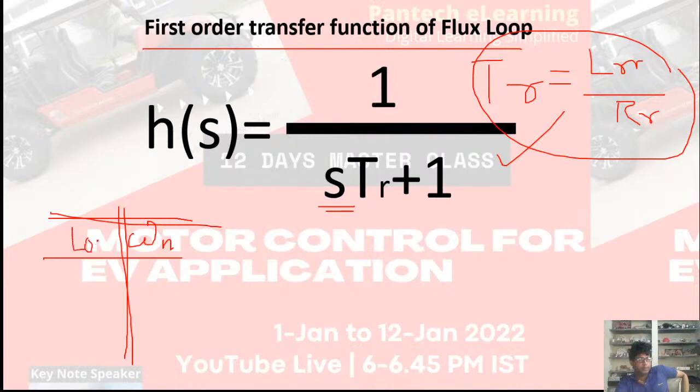So this is the flux loop. Sorry, first I will put the RPM loop, then the flux loop, and then the torque loop. The RPM loop, the speed loop, is the most sluggish loop.